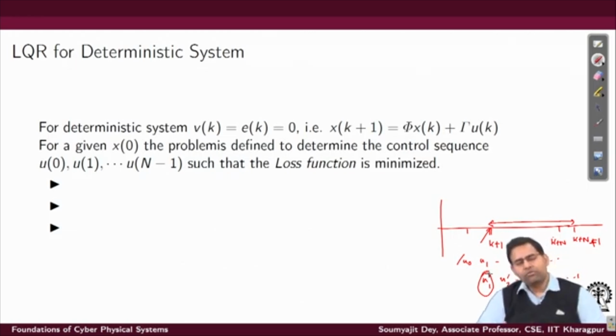So, you will receive a new measurement of state for the system. Then instead of again applying u1 and u2 and u3 like that in the k plus 1th state, with the new measurement you will create the optimization problem, and you will again create a sequence of control inputs, and you will apply the first of them. Of course, we are assuming that you have enough processor bandwidth available to do this, and we will work like that. So, that is the idea here.